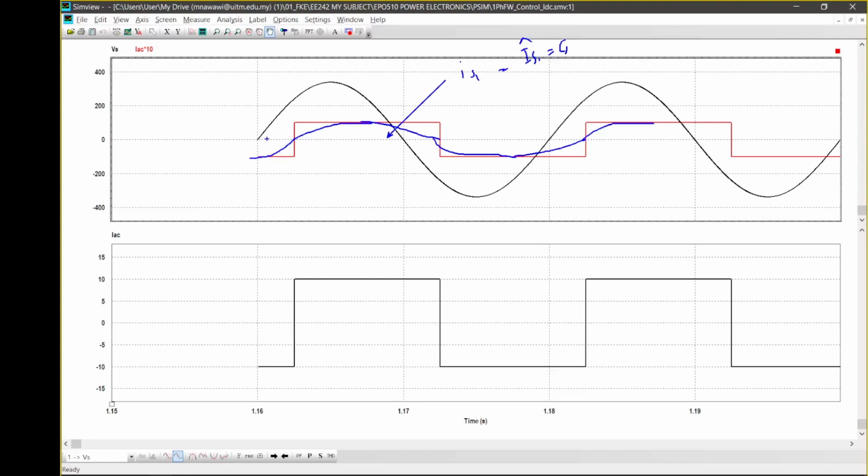Okay, so if you refer to that, there is an angle between the sinusoidal voltage and the sinusoidal fundamental current component, and that angle is known as alpha, isn't it? The firing angle. And before this, we have phi1 equals 0, isn't it? When the current is at 0, when we have a square waveform, 0 voltage here, of course, phi1 equals 0.